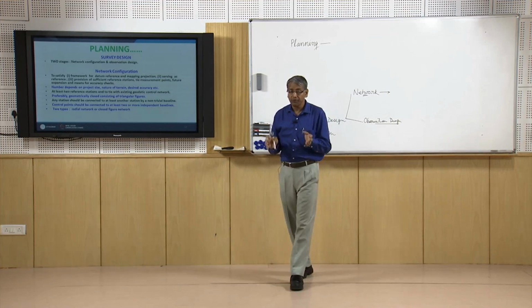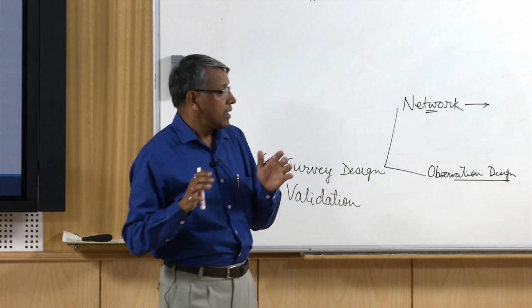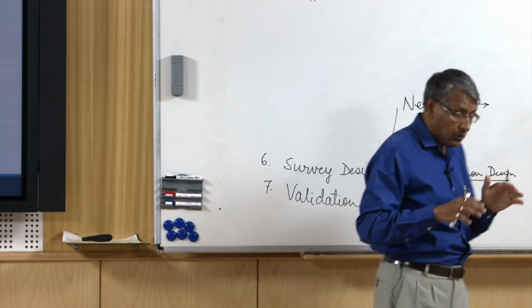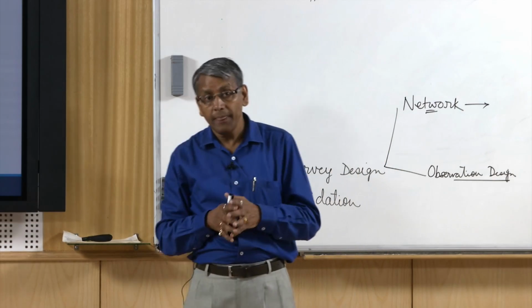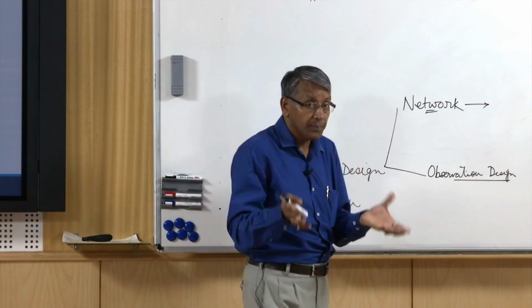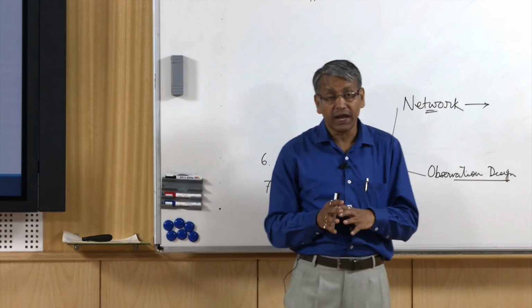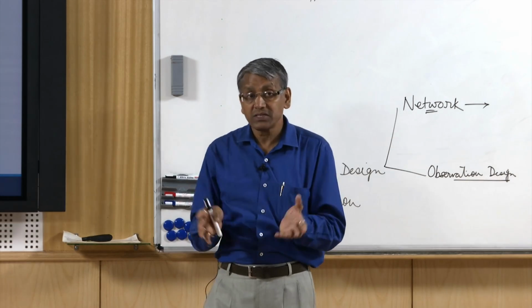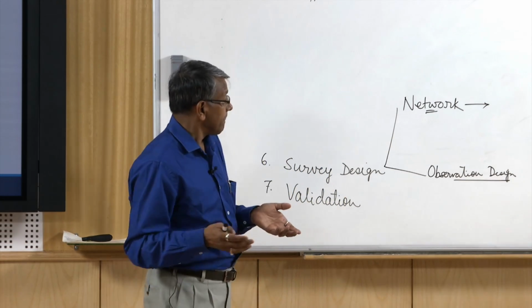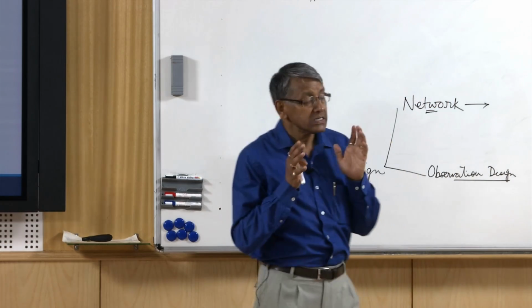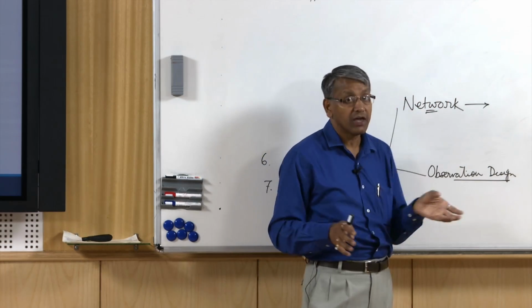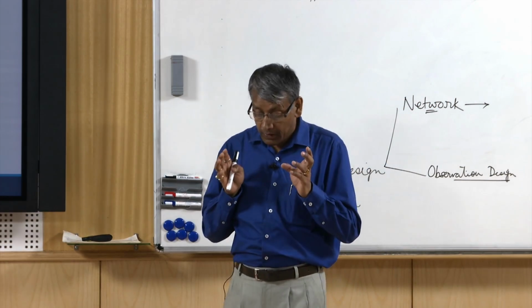The number of stations to be selected within a project area will depend upon the extent of the area, the nature of the terrain in which the project will be carried out, as well as your positioning methods, and finally the accuracy or the specification that the surveying has to achieve.